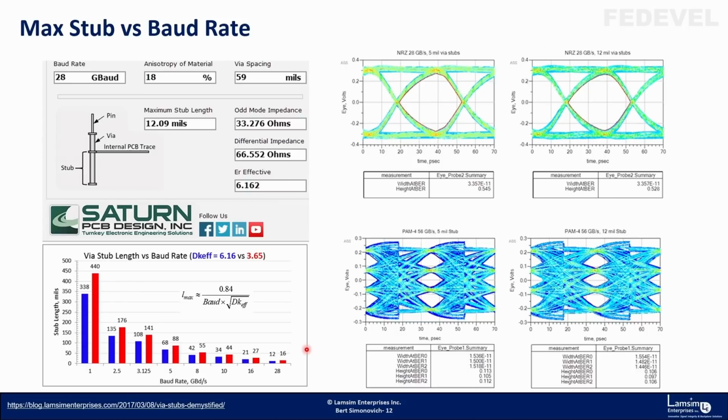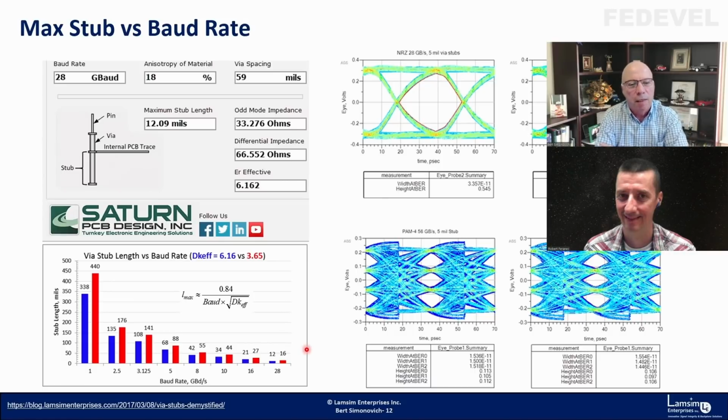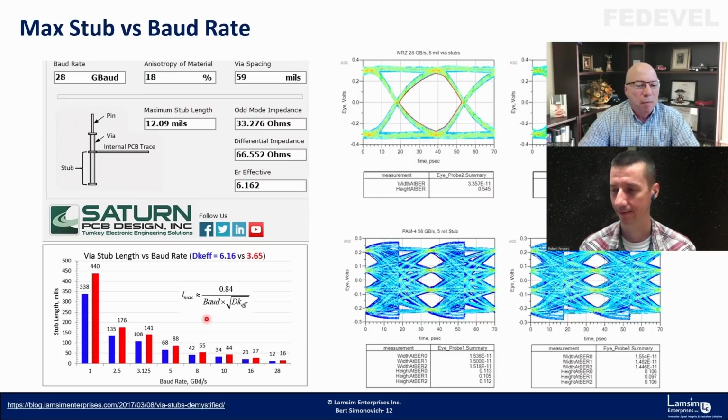Yeah, PCIe cards are very challenging these days. They're 62 thou thick, and you've got transmit and receive, so you have to watch the crosstalk, and you have to change layers to cross things. Everything doesn't always flow nicely, as you're aware. But really, the problem is the stubs at high speed. So you want to eliminate stub lengths as much as possible.